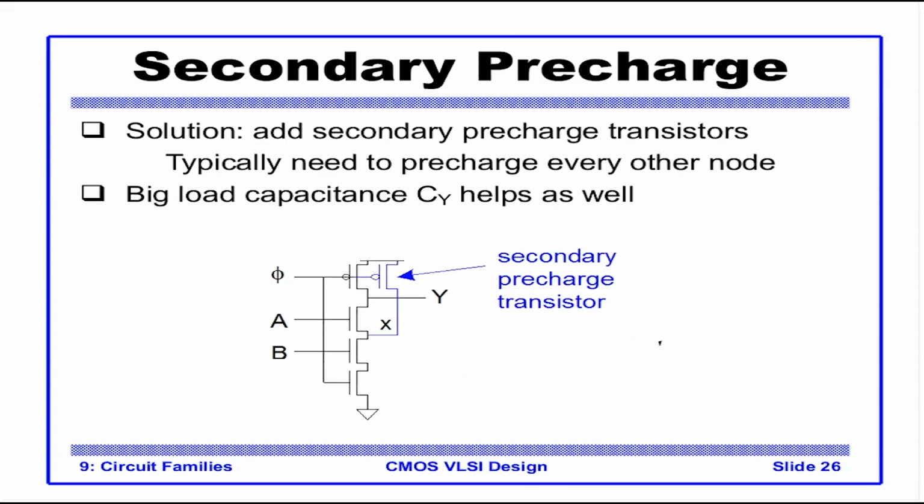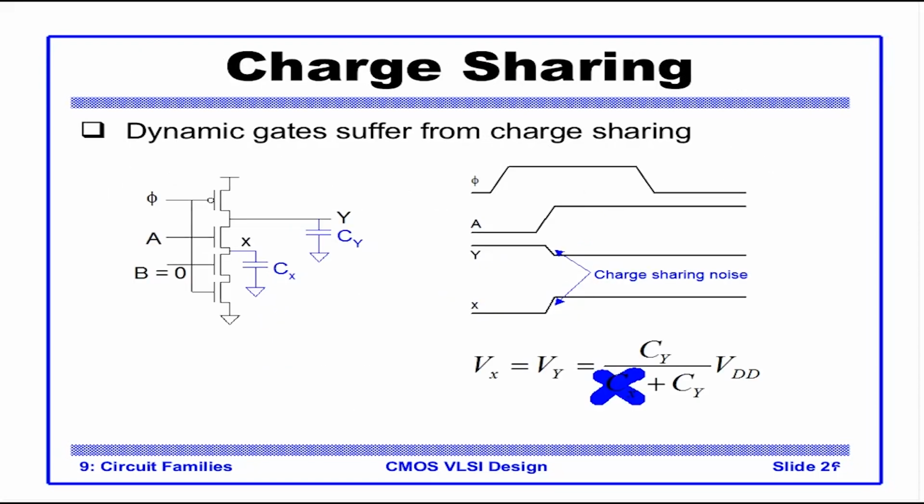To make Cx 0, what we do is we pre-charge node X. In fact, we typically need to pre-charge every such node. If you had like a 3 deep down logic, we have to pre-charge even that intermediate node. So all intermediate nodes have to be pre-charged to prevent this effect. What pre-charging means? Pre-charging means actually making Cx 0.